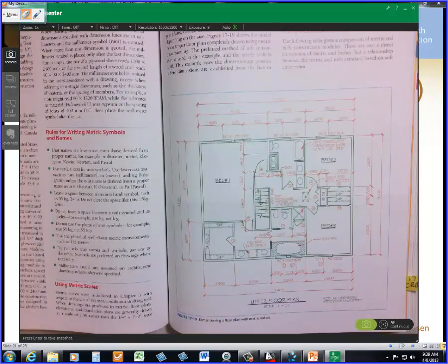No, that's the label for all of our dimensions and notes. 1/8 of an inch. In metric, what would it be? How many millimeters high? The actual paper measurement of our text. I'm going to convert 1/8 to millimeters roughly. Okay, it'd be 3 millimeters, and then your labels would be 6 millimeters.